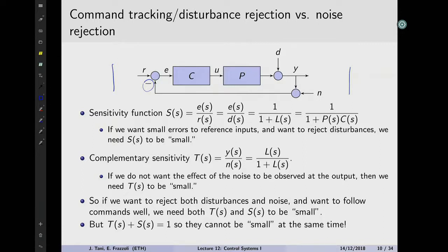So in our closed loop diagram, we have a bunch of different signals. We have the reference, the error, the inputs, disturbances, noises. Keep in mind that disturbances are represented like this in this diagram, but could very easily be represented as disturbances at the input instead of disturbances at the output. You'll find different schemes, different books will have different conventions, but both, of course, are legitimate, and actually it makes sense to have a disturbance at the input as well.